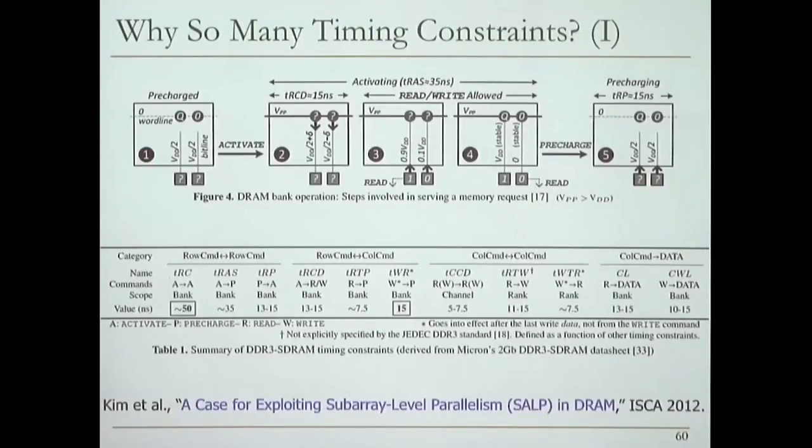After some point, the sense amplifiers kick in, and they start amplifying the data. They've sensed the data. They figured out that this actually is storing a 1. This has charge in it. But this other one doesn't have charge in it. This is storing a 0. At that point, you could actually issue a read command, right? And that's where the activate to read latency comes in. It basically determines when you can issue the read command after you've activated the bank. And that's there for a reason, because the sense amplifiers become ready to be read at that point. And in this particular DRAM, it's about 15 nanoseconds.